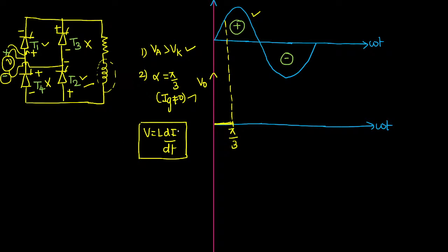But if you observe here, the rate of change of current with respect to time, the inductor will be continuously charging. Which one will appear immediately across the inductor, and which one will not? Basically, the inductor will show its moment of inertia only for current. Instantaneous changes will not be accepted in the value of current in case of an inductor, but voltage will be accepted.